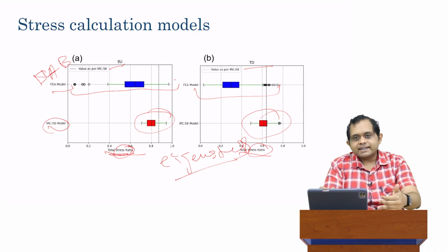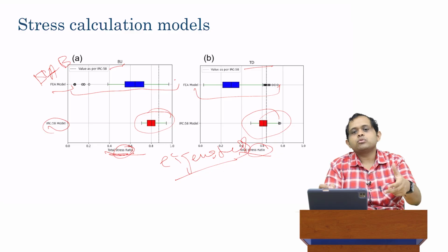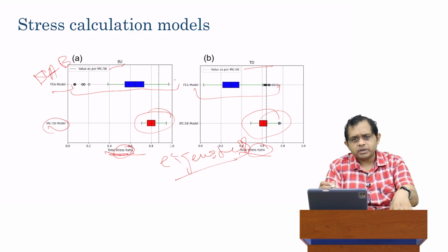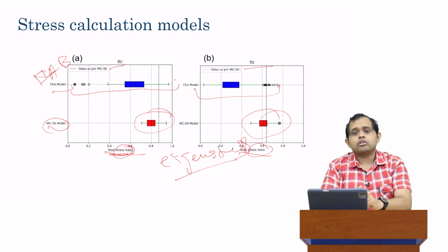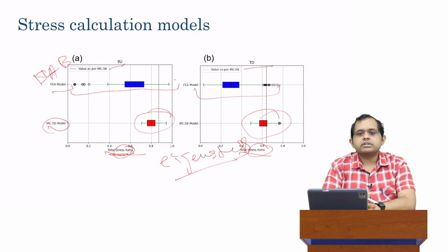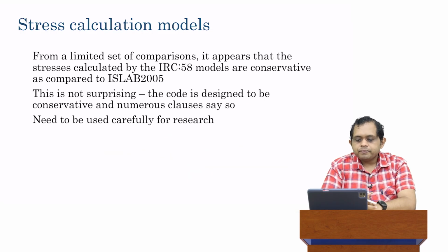So your delta T values tend to be on the higher side. The way you're accounting for the load configurations and the traffic distribution also tends to be conservative, and your stress calculations are also conservative. It's a very, very conservative way to do the design. I'm not sure it was strictly necessary to be that conservative. Anyway, that's overall how this works.